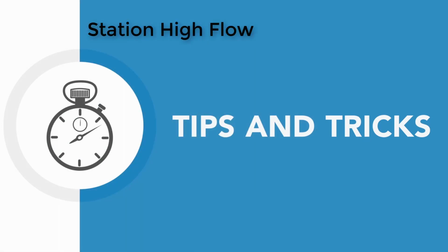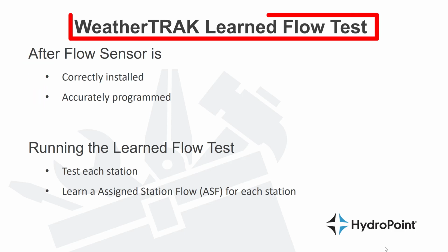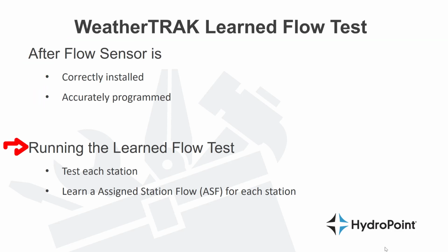Station high flow. With the WeatherTRAK system, after your flow sensor is correctly installed and accurately programmed, you'll want to run the Learn Flow test. With the WeatherTRAK Learn Flow test, you can either run all stations sequentially at the same time or each station individually to find the assigned station flow value for each station.